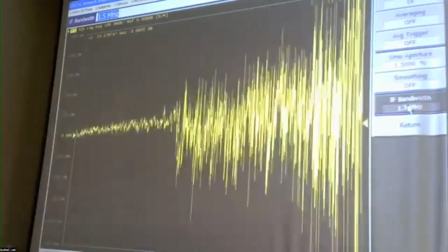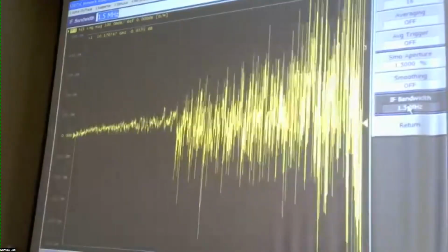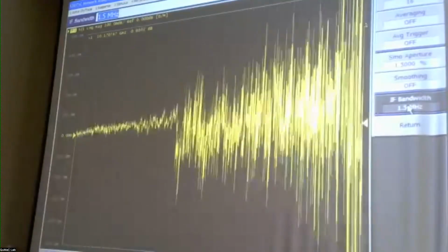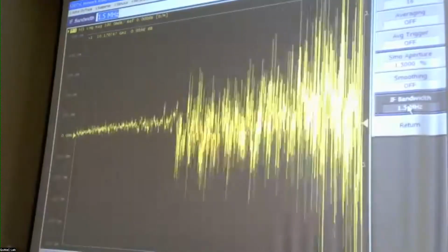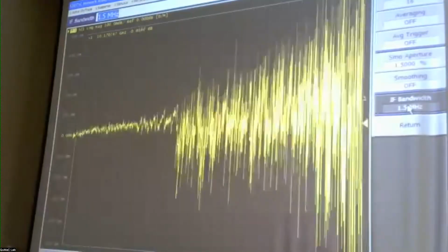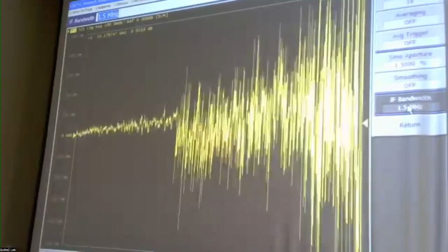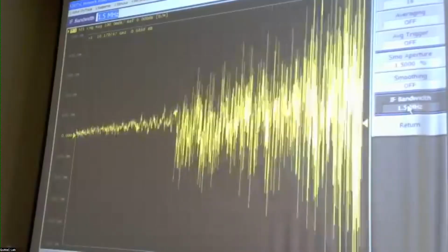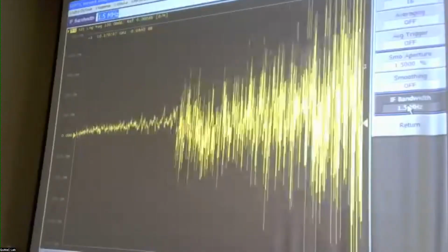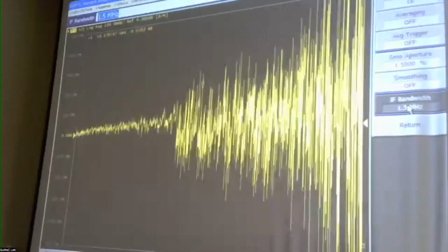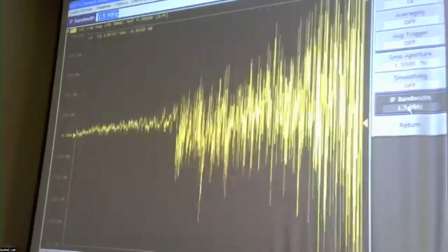This is a feature of the instrument. At higher frequencies, it's very difficult to design an active circuit which works over such a large range of frequencies, a single circuit. So what it will usually have are multiple amplifiers, multiple receivers, which are shifted automatically when the frequency changes, and they will have different noise properties. So the receiver noise is much better at lower frequencies, but at high frequencies it's quite bad, and it gets really bad at very high frequencies.